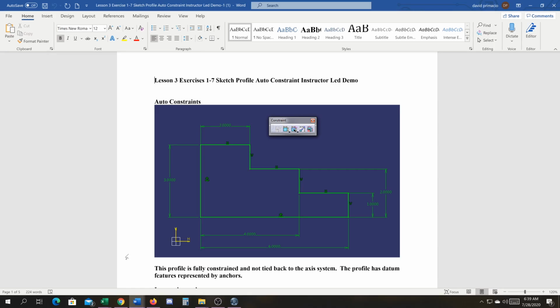If you understand drafting and you understand dimensioning, you can really manipulate the auto constraints. If you want to do baseline dimensioning or chain dimensioning, it's really good for that. One of the problems it has is dimension to points, dimensioning to angles, dimensioning to elements that are not going to come off your datum. So if you manually stick those in, it will pretty much do the rest for you. So you got to give it a little guidance.